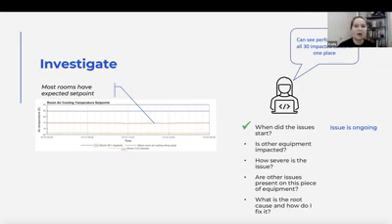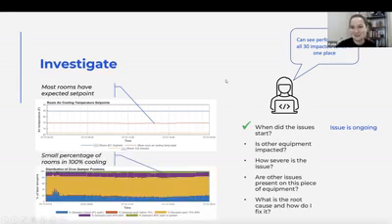So if people were hot, I would anticipate they would take that slider and they'd push it down. They'd say, I'm too hot, I need cooling. So you'd expect these 3 points are showing you the minimum set point that somebody has in there of those 30 zones, the maximum set point someone has, and the mean. So I would expect this mean to be low if there were a lot of people on the campus demanding cooling, and it's at 75. So I don't think very many occupants are sitting in their offices too hot, assuming they know how to use the slider. But let's go to another picture just to verify that.